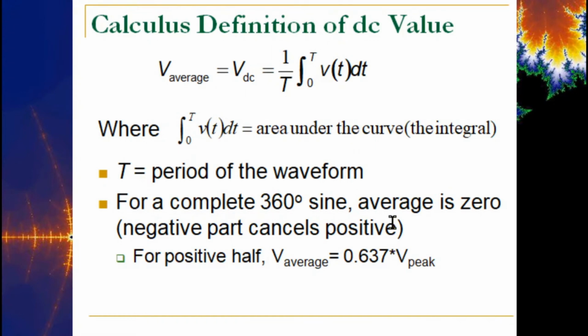So Ben asks, is 120 volts an RMS voltage? It absolutely is. If you take 170 volts times 0.707, you will come up with 120 volts. So your meter is meant to read in sine wave RMS. If you were to take your DMM, put it in the 200 volt AC range, and plug it into any outlet in your apartment or house, you should read 120 volts RMS.